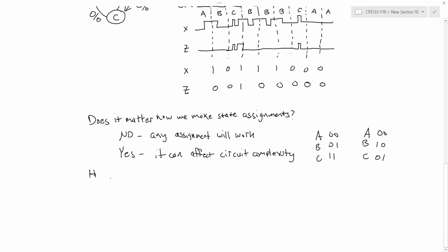Okay, and then another question you may have is about the don't care states. Does it matter how I use them? Are they really don't cares? So first question would be, how could we ever get into a don't care state? And there's actually two ways this could happen. It could either happen on startup, or it may also happen because of an error that I can get into one of these don't care states.